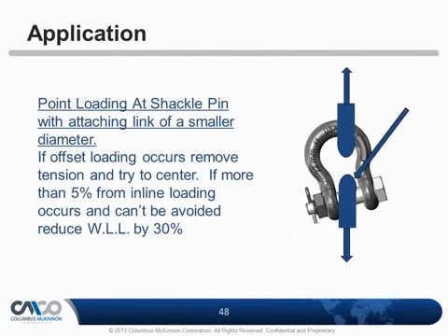So again, off-center lifts, you can see here shackles can twist. I had another slide showing that where it was a full side load, but we really want to avoid that. So we try to get it in line as best you can, and if you can't, take your proper reductions, be on the safe side, and reduce the working load some based on the charts that we just showed you, or call your manufacturer of the shackle and get that information